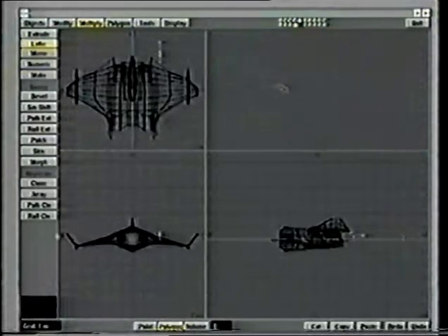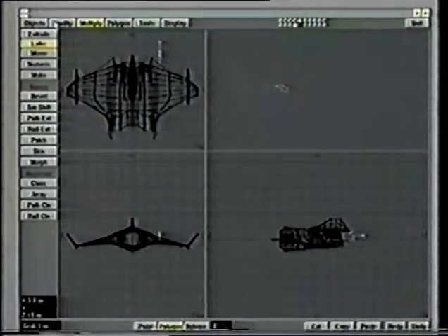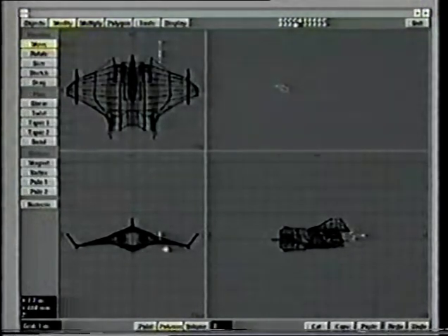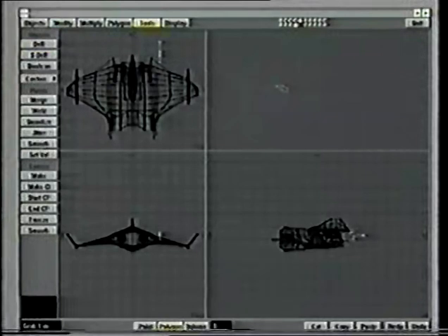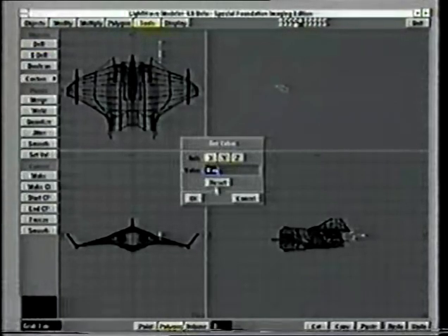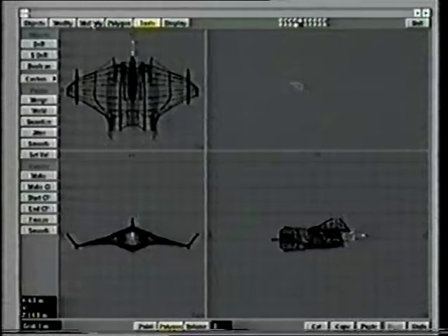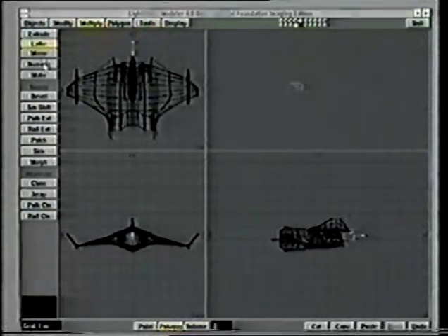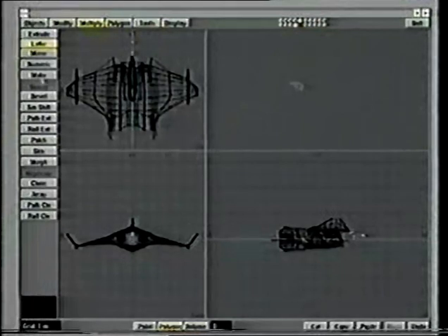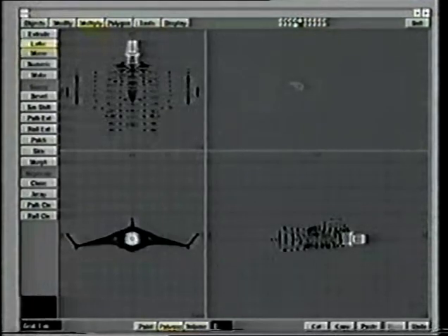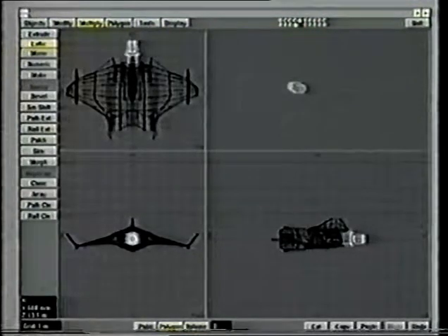Let's make it. That's not right. Ah, I see why. Now I built that off center axis, so I'm just going to move it into the middle. Probably the quickest way to do that would be to set val on the x-axis to 0 meters, bang, and it brings it right into the middle. Now we can multiply, lathe, numeric, okay, and make. Okay, there it is.